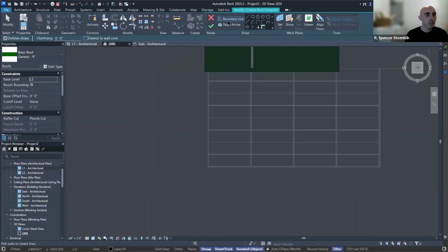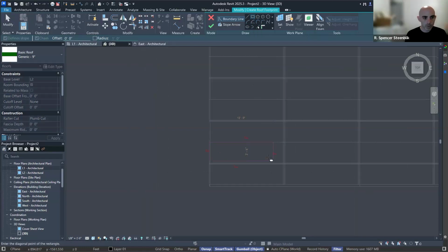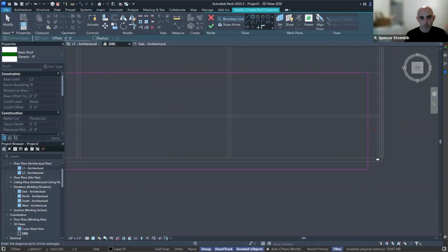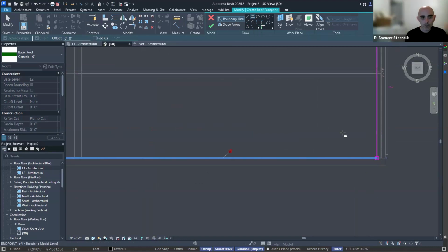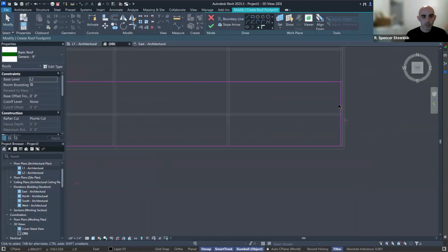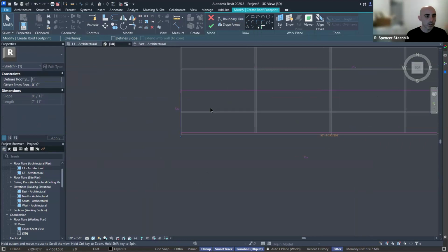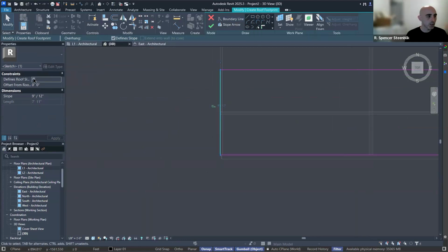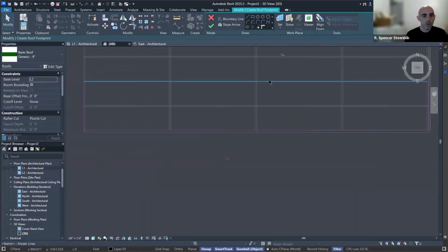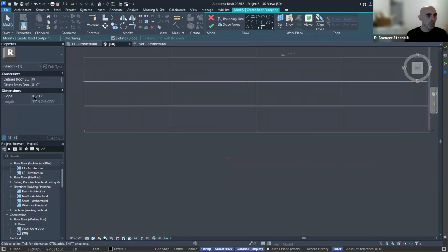So here we have our roof, and we can set a boundary. So this is going to be basically what we want. Okay, and then we're going to hit escape a couple times, make this not a slope defining angle. And this one also, we want to uncheck that slope defining angle. And then we want to choose this to be 612, which I think is 45 degrees slope.